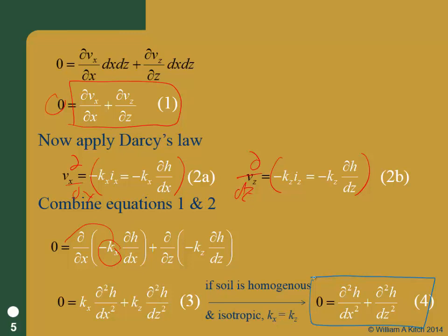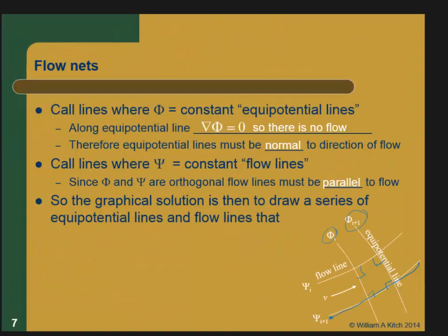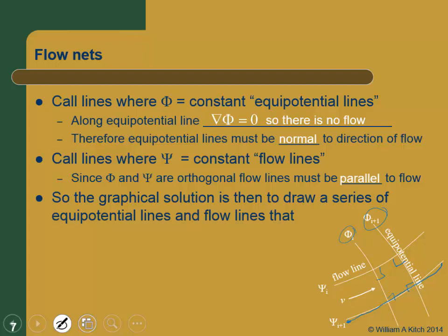Now, in addition to the general solution, what do I have to satisfy to have the exact solution for a specific flow, for any differential equation? You have to satisfy the general solution. Then what do you have to solve for? All the constants, which are your boundary conditions. So to have a solution specific to a problem, I need to draw two families of lines, each family always parallel to itself, that intersect at right angles, and I've got to meet my boundary conditions.